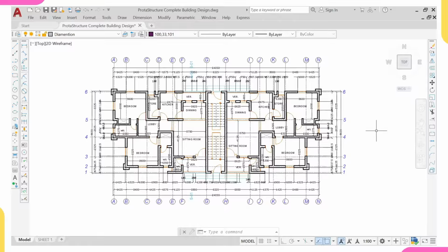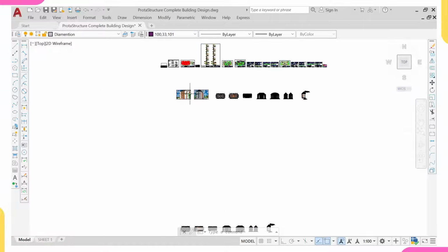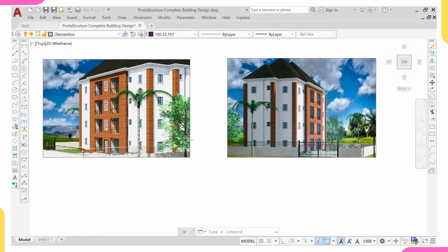These are the things you study in your architectural plan. Also study whether your architectural plan has a basement, because if it has a basement, our structural framing must be done on the ground floor plan, not on the basement plan. And if it has a basement, you should know that you'll be having concrete walls to retain the soil. Also, you check whether there is an offset or any cantilever. But if you check here, there's no cantilever in this building.